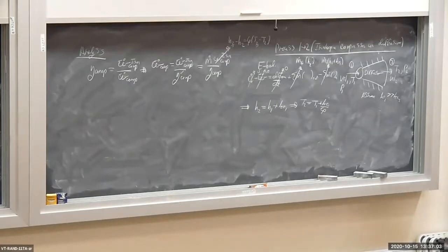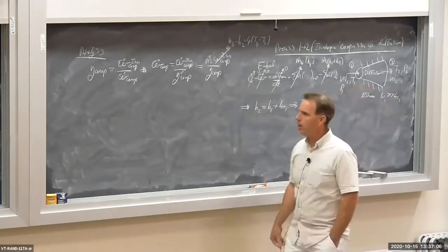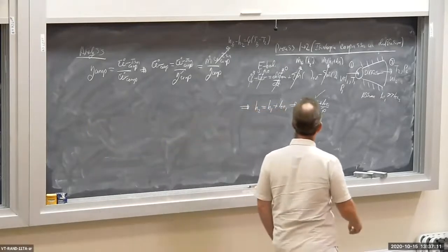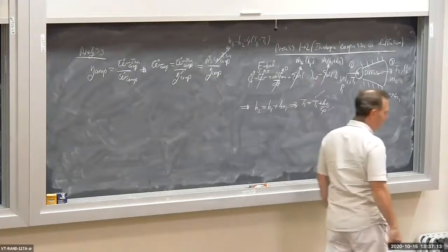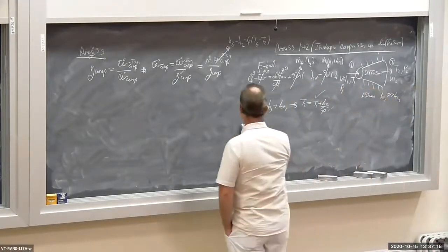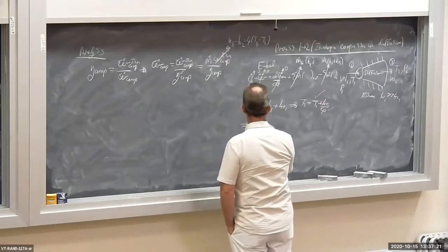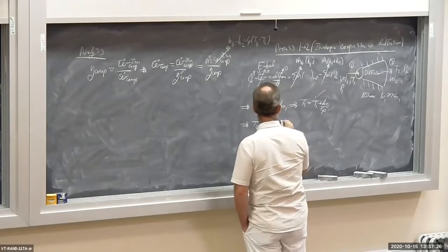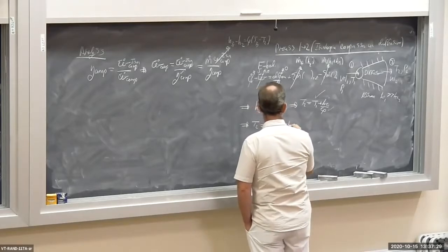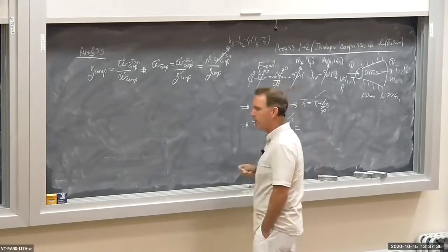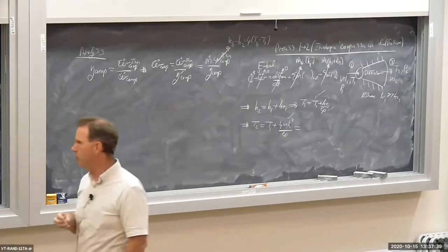I have T1. T1 is 241 degrees Kelvin. I have Cp as well. The specific kinetic energy at the inlet, well, I guess I need to work on that. T2 is equal to T1, and I'll expand the kinetic energy term: that's 1/2 velocity 1 squared over Cp. I have the inlet velocity. The inlet velocity is 320 meters per second.